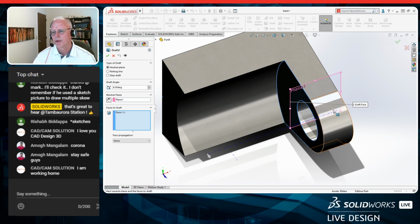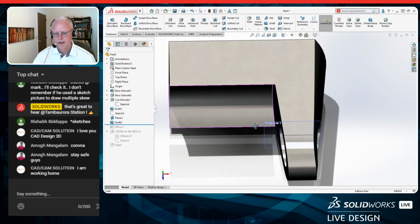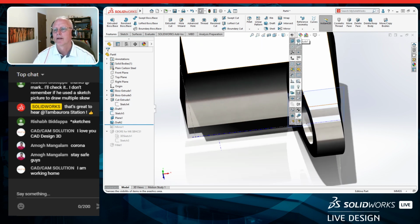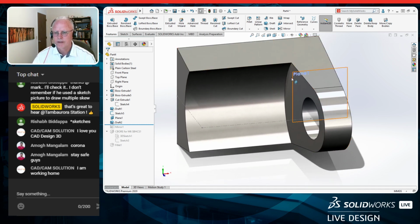Change my direction of pull. I didn't watch my little arrow here for direction of pull. 8 degrees of draft. And what that did then is it added that 8 degrees draft by removing material. Let's check it with this guy. Show this sketch here. Turn off my temporary axes.